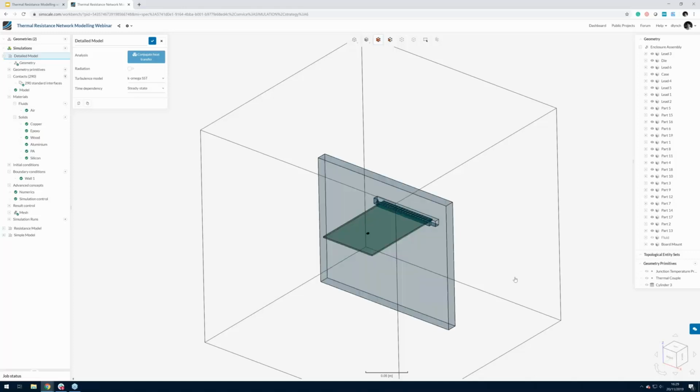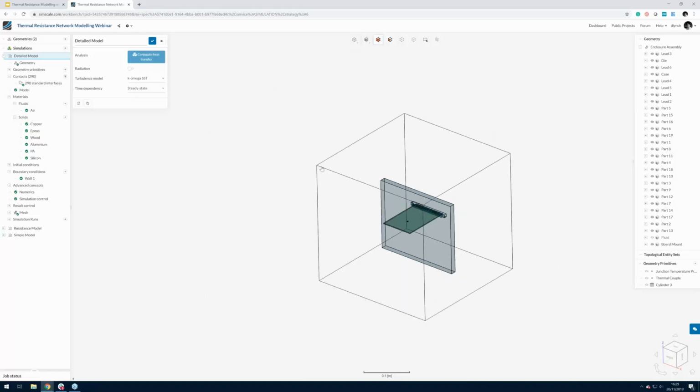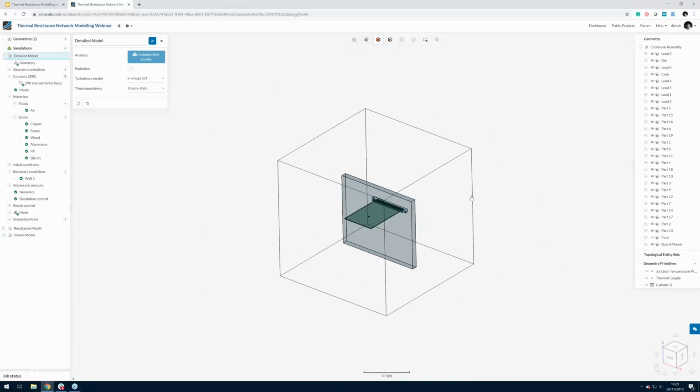So how do we set this environment up? To start this process, if we didn't have this information from the manufacturer, how do we start? There's actually quite a lot of standards involved in defining this test environment. Most of those standards come from JEDEC, which publish a list of standards for these test environments for the board, for the sort of scenarios that you put the simulation or the test through. I can't share that with you. You have to go onto their site, register and view the documents yourself.